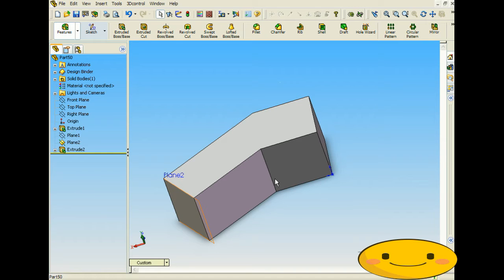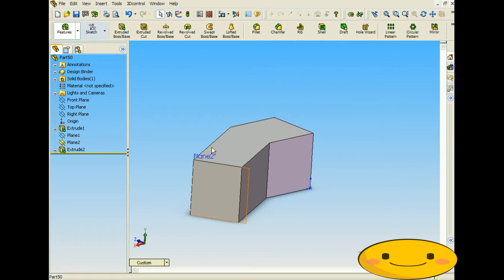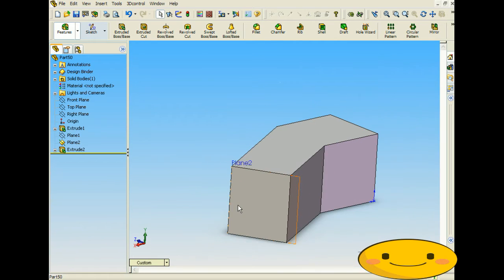All those lines that come onto your view are directly perpendicular to what you're seeing. You're pulling straight out. Like I showed how the 50 mils turned into the 43.3, that's how much of the line you're actually seeing at that plane and at that view and orientation. So it's a wonderful feature to pull out other features from other parts, components, and sketches.